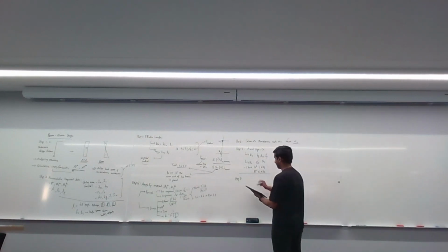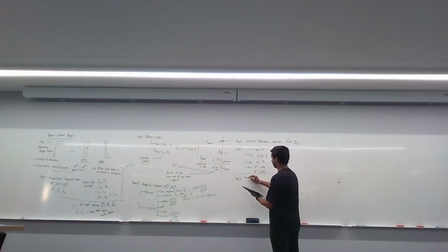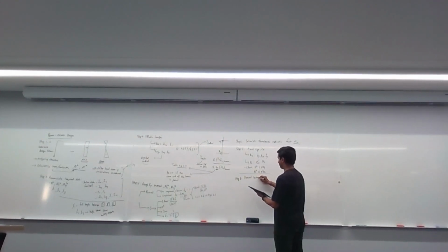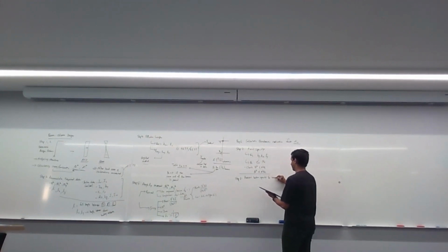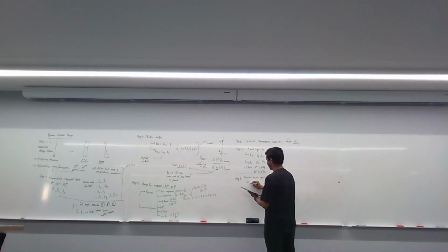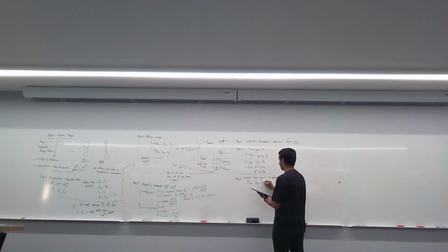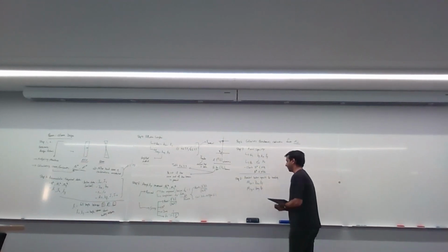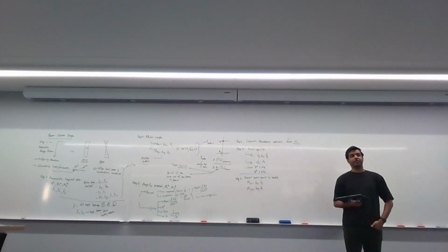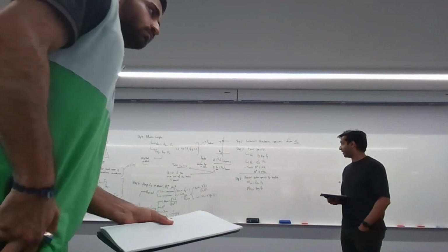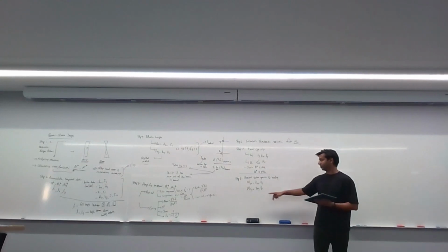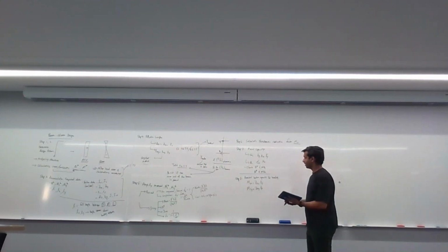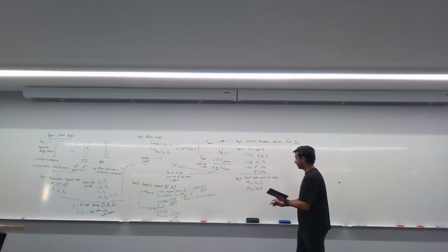So the nominal section capacity for bending is MSX, which is ZEX Fy, and then you have MSY, which is ZEY times Fy. Basically your section modulus Z multiplied by the yield strength Fy will give you your various capacities.